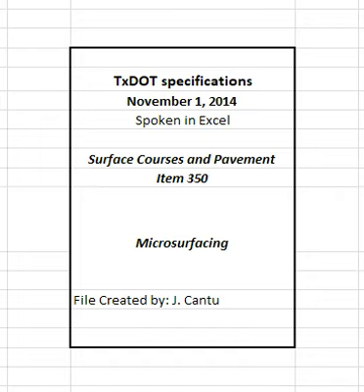4.12 Miscellaneous areas. Use a single batch type laydown machine or other approved method to place materials on ramps or other short sections. Apply tack coat uniformly at the rate directed by the engineer when shown on the plans, or lightly dampen the surface with water before placing the mix when tack coat is not required. Provide 100% coverage that is uniform in appearance and comparable to that produced by the spreader box.